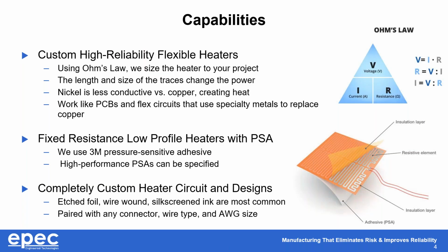These products are very similar to flexible circuits, where with most flex circuits, the conductive material is copper. Copper is highly conductive. Our heating elements use various different alloys that are higher resistance, and therefore, when power is passed through them, they generate heat.